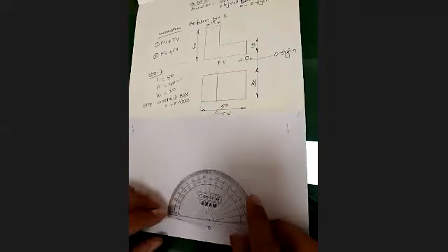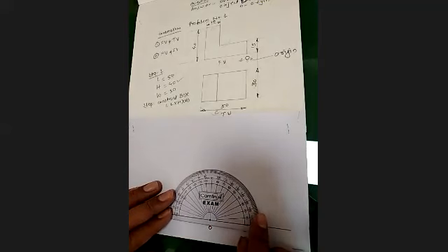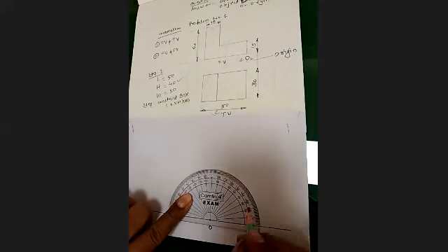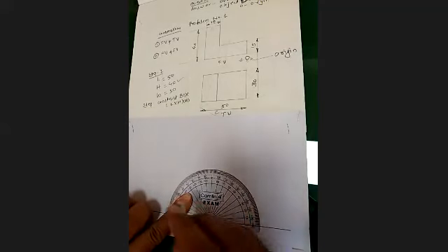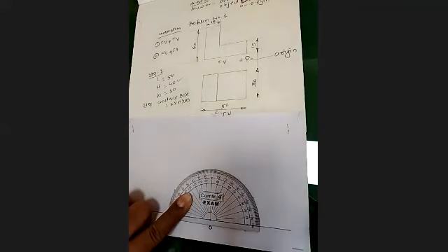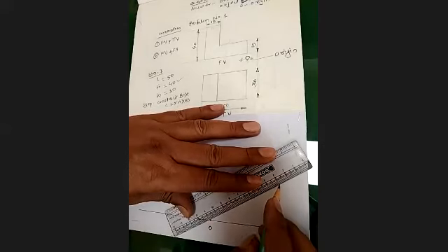So what I will do, I will take it later on, but first of all, I forgot to tell you that you just set a compass with this O, and on this horizontal line get 30 degrees on both sides. This 30 degrees, you are going to get on both sides. Okay, take this 30 degrees, draw a line passing through this point.